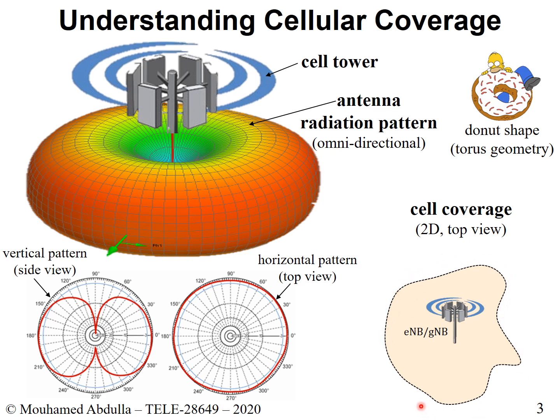If you have buildings, and trees, and other types of obstacles that inhibit or hinder your signal, then you'll end up having things like this, where you have certain holes in stronger areas. This could be caused by reflection, scattering, diffraction, or most importantly by shadowing.